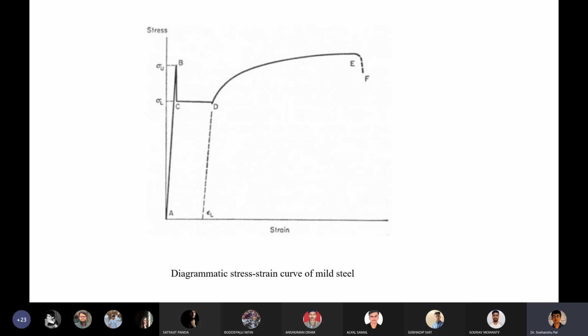And the point capital F is marked to indicate that at that point normal ductile fracture is going to occur. As we will see, there are numerous variants of this stress strain curve, dependent on the material, temperature, grain size, and other metallurgical variables like strain rate. All of these are going to influence the stress strain plot.